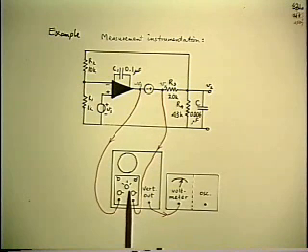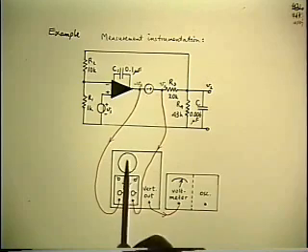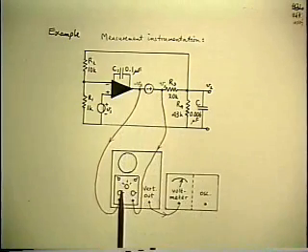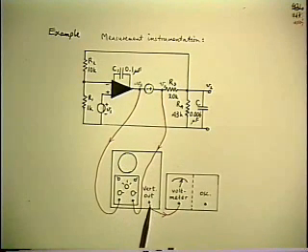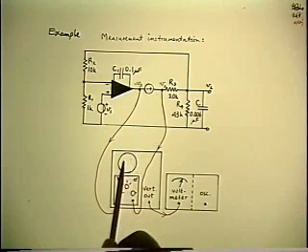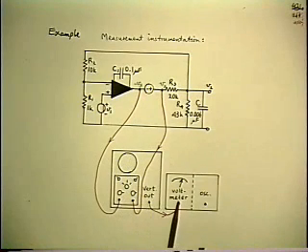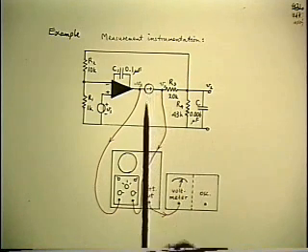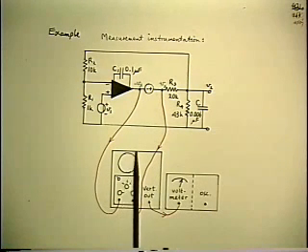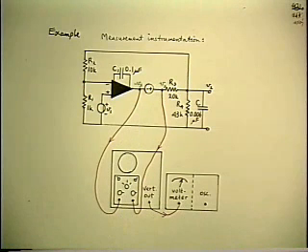And what you have available is a selector knob that says you can observe on the screen either Vx or Vy. And Tektronix also conveniently provides a vertical output, so you not only look at the waveform on the screen, but you plug it into the analyzer, so you measure it also. And of course, to measure the magnitude of the loop gain at any particular frequency, you simply switch from one channel to the other and take the reading in dB and subtract the 2 dBs, and that gives you the magnitude of the ratio. That's straightforward.